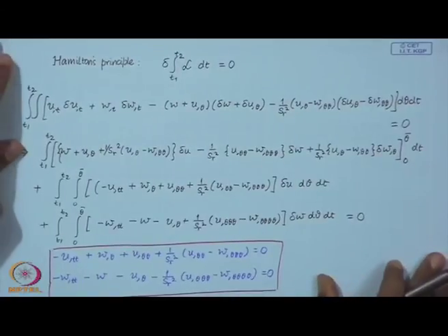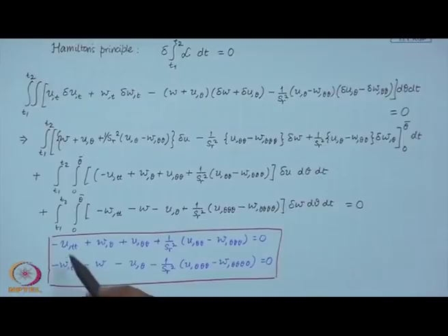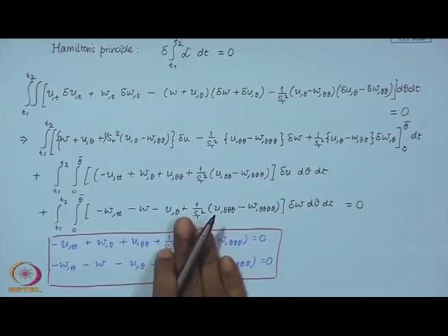Now, you can once again see the coupling between the circumferential and the radial directions. Now, since these equations are non-dimensionalized, you can look at the contribution of these terms in the equation. Now, if the beam is very slender, which means slenderness ratio is very high, then these terms will become insignificant.